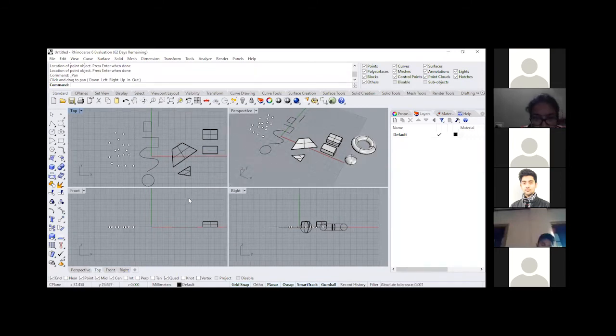So that's for the ortho viewports. And for the perspective viewports, if you use the right mouse click button, it's going to orbit like this. If you want to pan over here in the perspective, you can click the right mouse along with shift. That allows you to pan around in the perspective viewport. Does that solve your doubts?